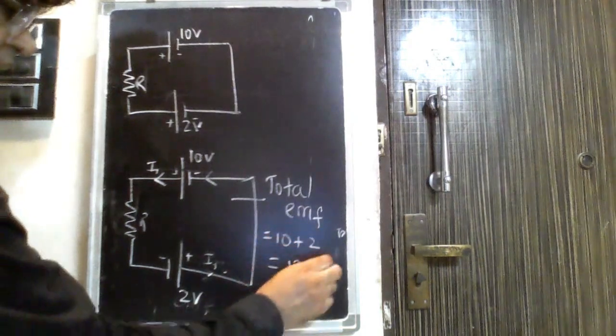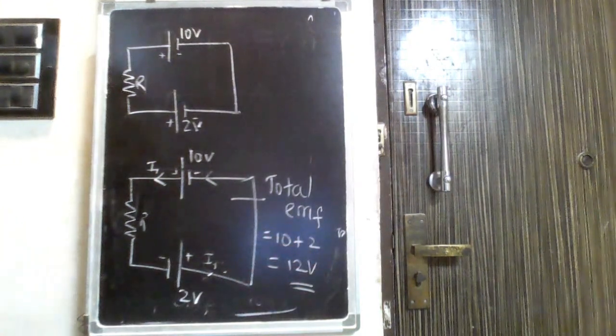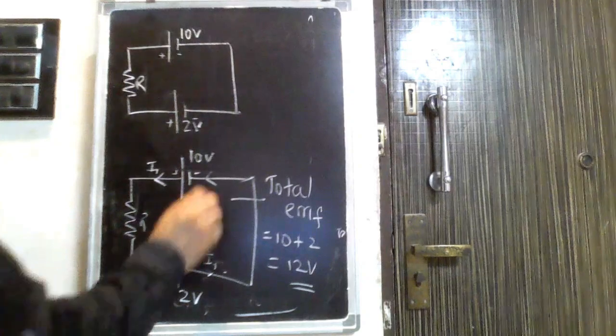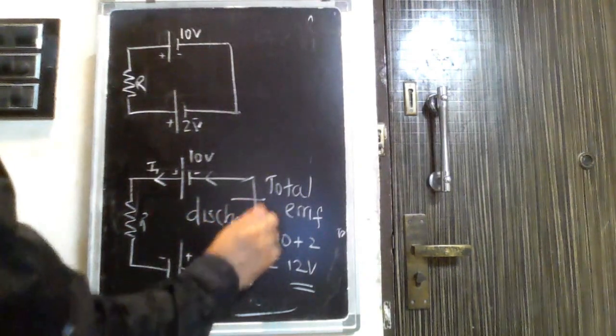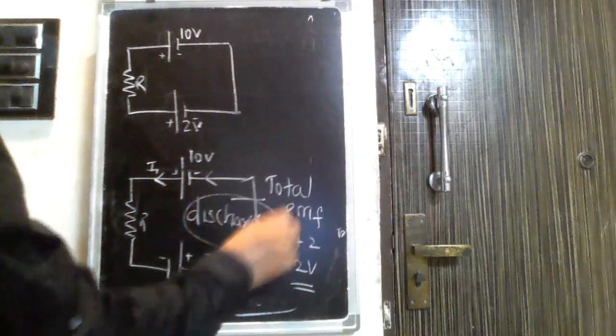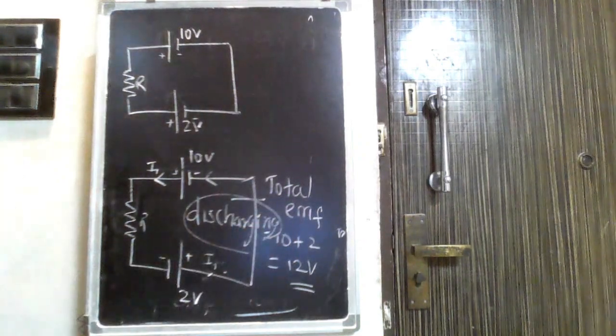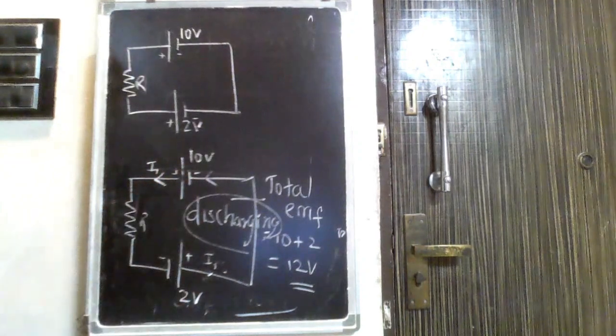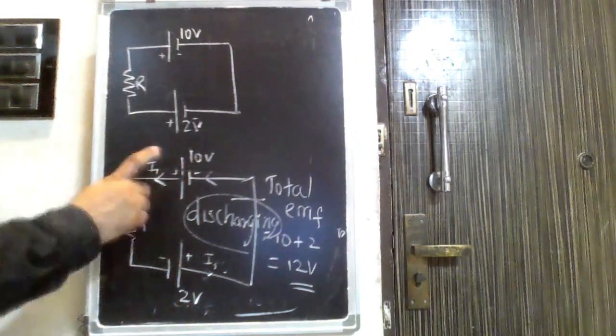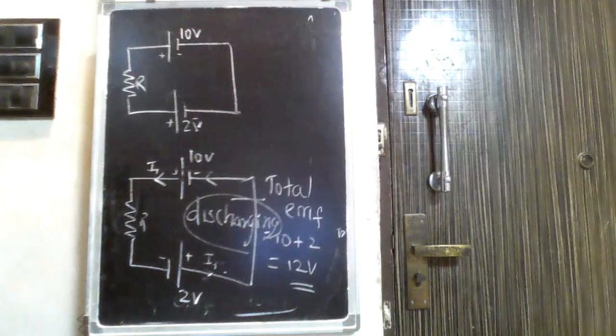So it's very easy here. They are helping each other. Here both the batteries are sending current out. So both the batteries here are discharging. So I have no confusion here. My discharging is happening. So every time current goes out of the battery, it's discharging. So both the batteries are discharging. So this will be V1 equals E1 minus I R1. This will be V2 equals E2 minus I R2. So here both are going to be V equals E minus I R because both are discharging.